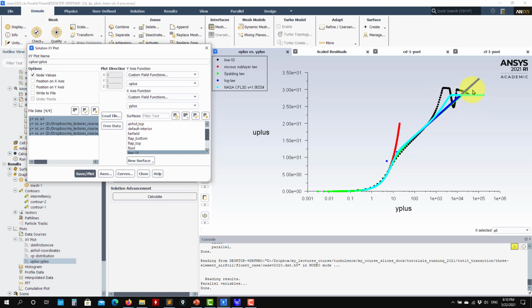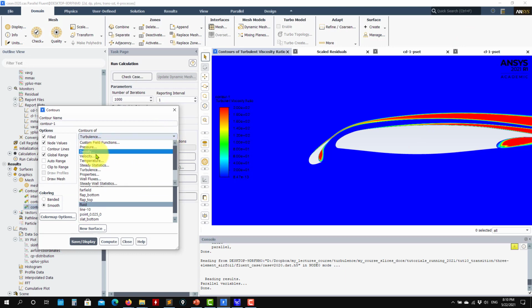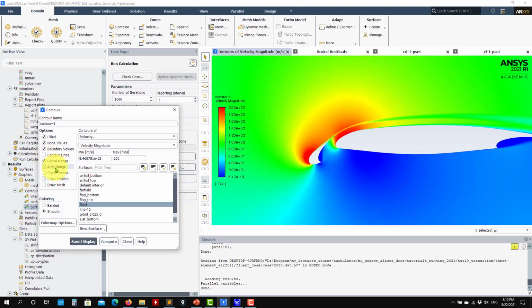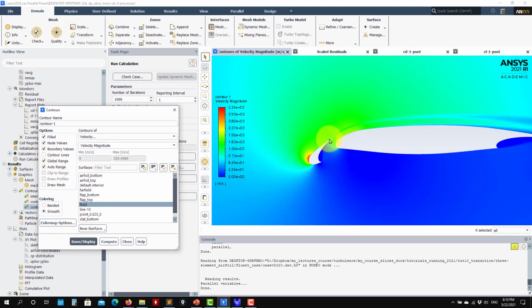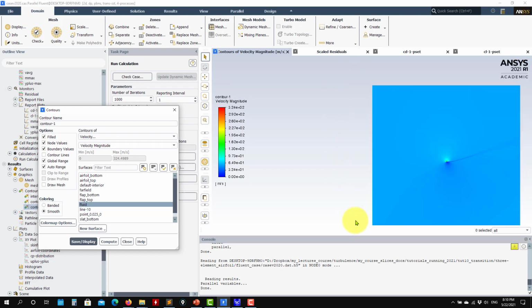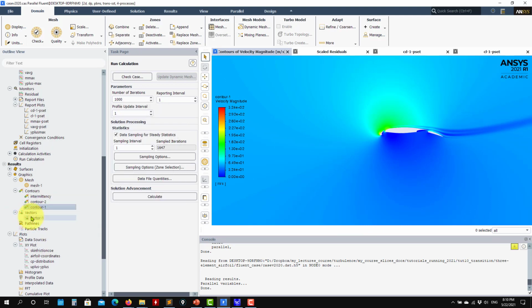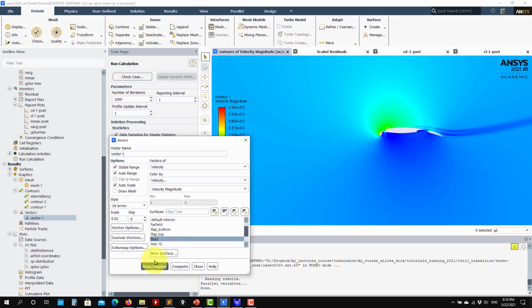And then you have this funny behavior, but this is mainly due to the separation, to the secondary jet that is influenced by the velocity there. Just to remind you, it's this secondary jet that you have here. So remember that you have the flow like this. It's a flow entering at a large angle of attack. Here you see the influence, and probably you can also put vectors just to see things better.